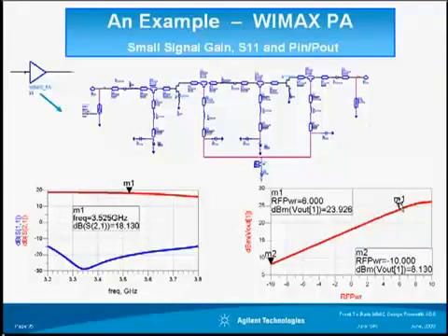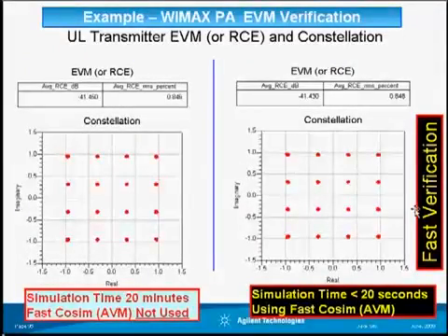So at around 6 dBm, I want to measure what is the EVM of this PA. As I said before, I just insert the PA in the template and hit simulate. And these are the results. Notice I have two results, on the left side and the right side. Okay? Why? Because there are two different ways available to simulate and extract the results.